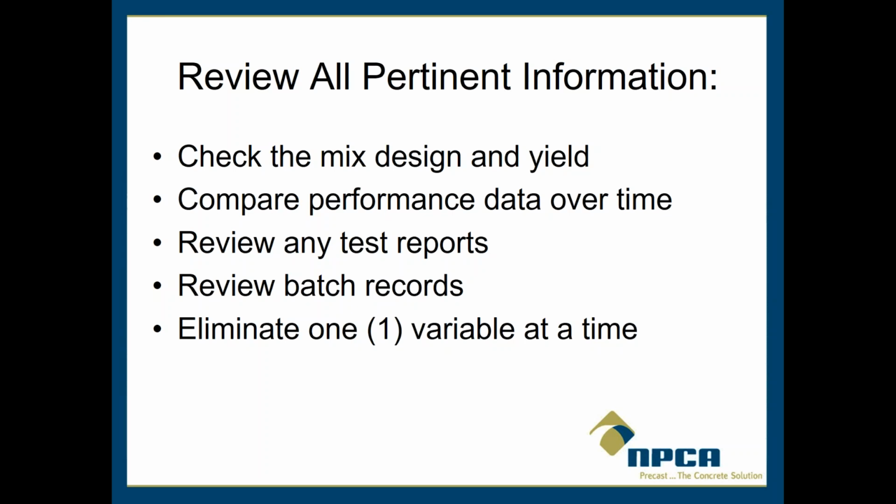One of the first things that I think should happen is just check the mix and the yield. So is it proportioned properly? Are the materials put in the batch computer correctly? If I have a complaint about someone telling me the mix is too bony or too rocky or something like that, just check it. Let's make sure that the mix is put in properly, that it's yielding properly.